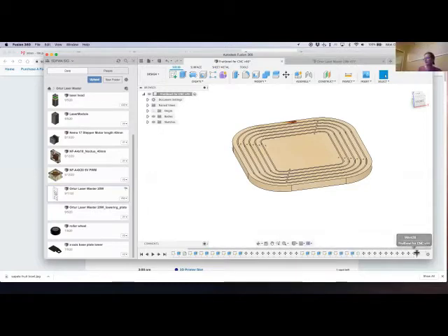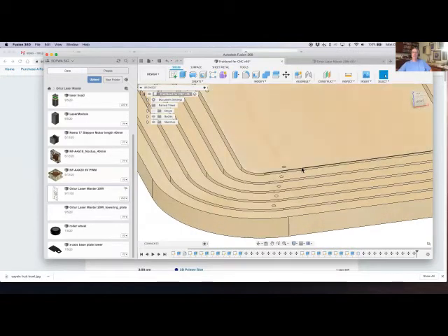Correct. Yeah, I used VCarve, and I used this vector all the way around, and said cut a profile outside the line using the 1/8, and I gave it a pass depth. In this case it was 3/4 of an inch, and I probably used, say, a 75 thou pass depth. It would take 10 passes to do it. I have not learned in Fusion 360 how to do what you just did using their CAM.